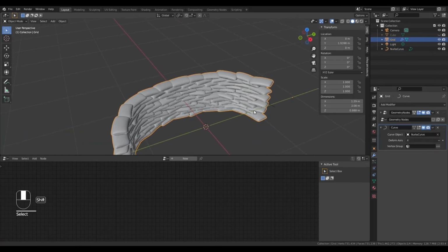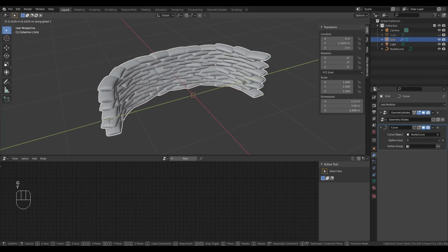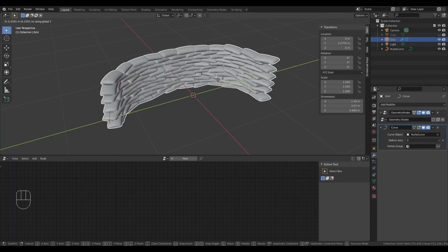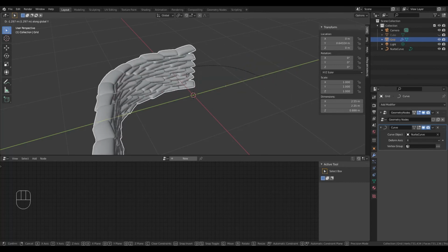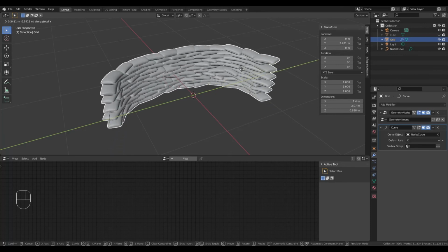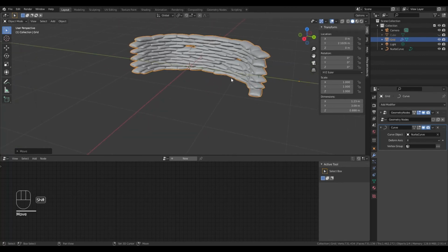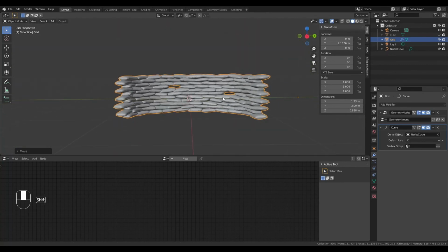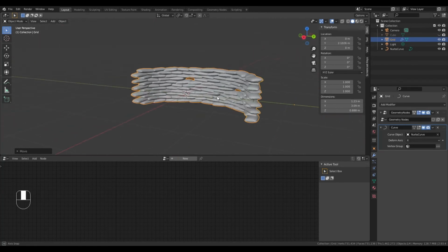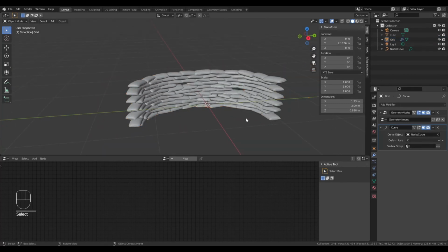It's a little bit short on the Y side, so I'm going to move the wall over on the Y axis. You can see that as I go back and forth, the wall is following the curve precisely. So I'm going to say put it right there. So now we've got a cool little curved section of our sandbag wall with some holes inside of it.